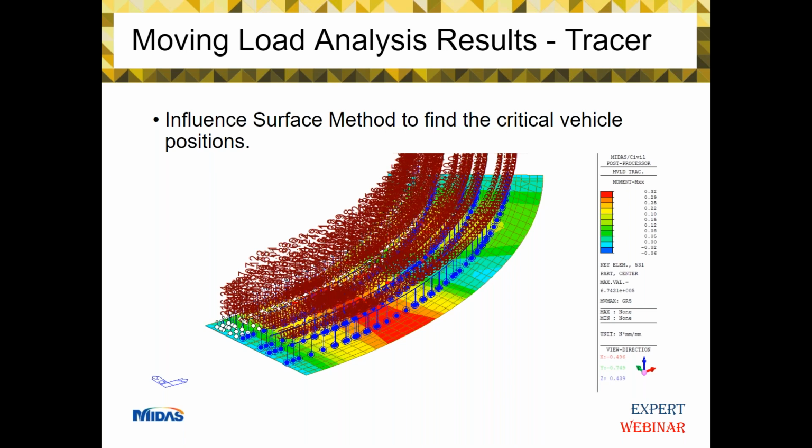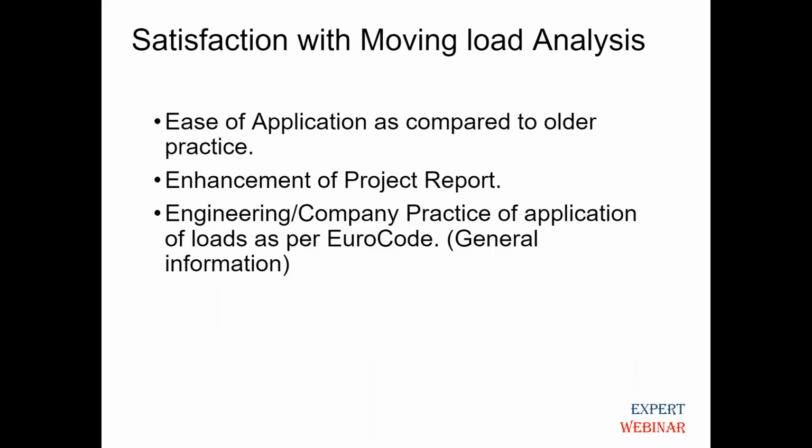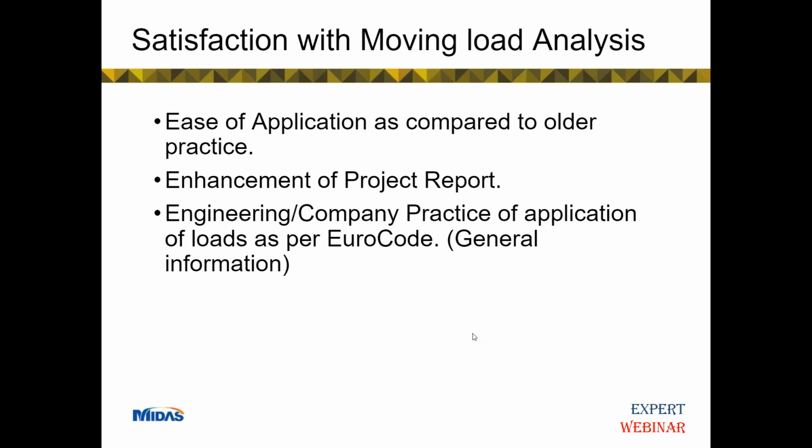Of course, the satisfaction with moving load analysis is of application as compared to older practice. As you've seen, there's an enhancement of the project report, because then your project is graphical and easily understandable. In engineering or company practice of application of loads as per Eurocodes, the program follows strictly what the code says. If it says, when you're straddling the vehicles in 2 notional lanes, move them maybe 0.5 meters away, the program will go as per the code. It will carry out the analysis as per the code.